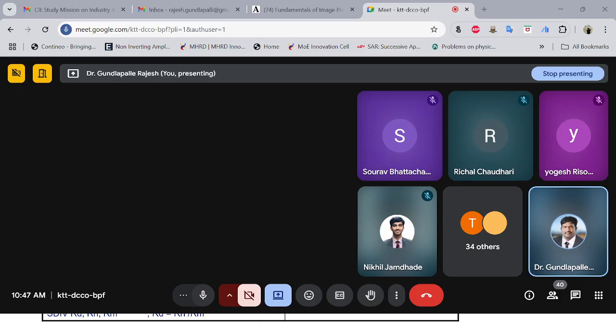Then we have subtraction, where Rm contents will be subtracted from Rn. Then we have what is called reverse subtraction, where the opposite is done. In a normal subtraction, Rm will be subtracted from Rn, that is Rn minus Rm, whereas in reverse subtraction it will be Rm minus Rn. So Rn will be subtracted from Rm.